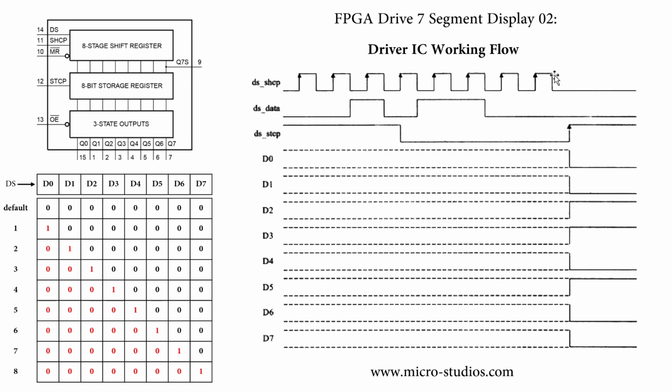At last, when all the data is stored in the shift register, we use the storage clock at this position. We use the storage clock to output all the data, put all the data on the parallel data bus. So it means you can control when you get the parallel data here.